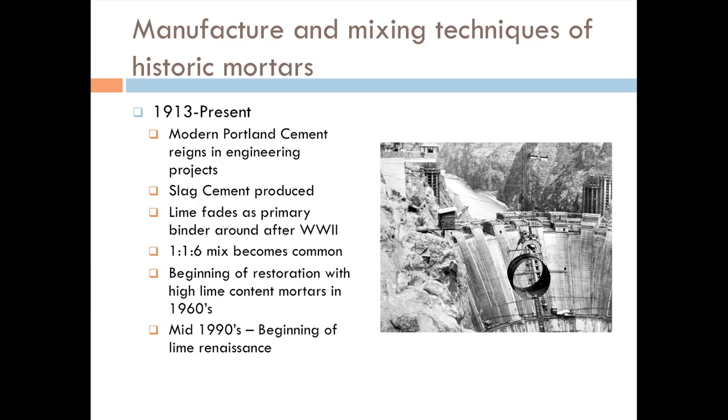Well, you're getting more tensile strength in Portland, and it cures in about 30 days. And hydraulic lime cures in how long? And does it ever attain that compression strength? It can. It depends on ideal curing conditions, and I would argue that even this mix of lime, cement, and sand doesn't always end up reaching its desired strengths either.